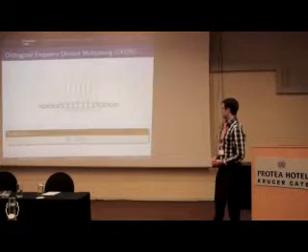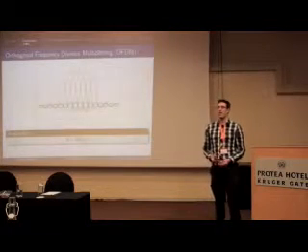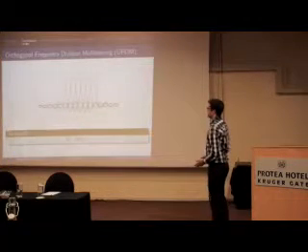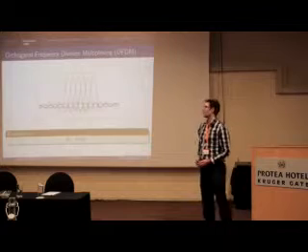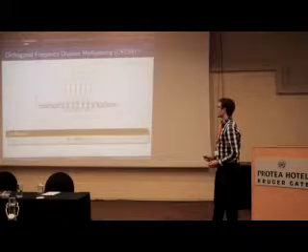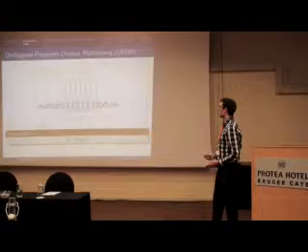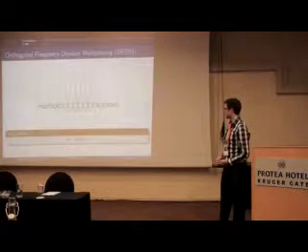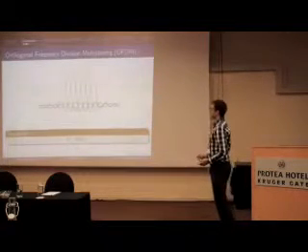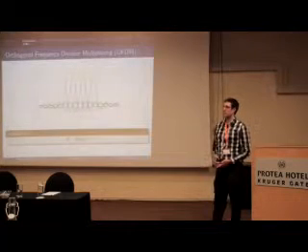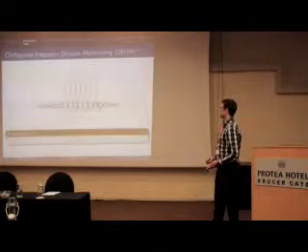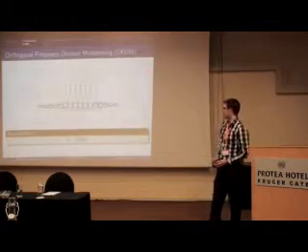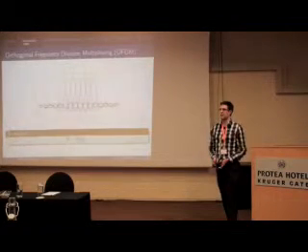multiplexing method, and it's an improvement over other multi-carrier methods such as frequency division multiplexing, whereas there are no gaps between multiple carriers. So the way OFDM works is the peak of one carrier coincides with a position where all the other carriers are zero. This allows us to easily extract each carrier at the receiver side. And we get to compact twice the amount of data in the same bandwidth as a traditional frequency division multiplexing method. So the total bandwidth used by the system is just the number of sub-carriers multiplied by the frequency spacing between the sub-carriers.